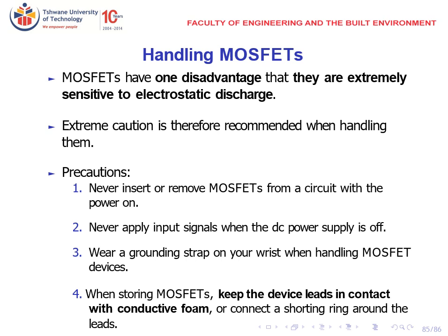Never apply input signals when the DC power supply is off. Wear a grounding strap on your wrist when handling a MOSFET device. When storing MOSFETs, keep the device leads in contact with conductive foam, or connect a shorting ring around the leads.